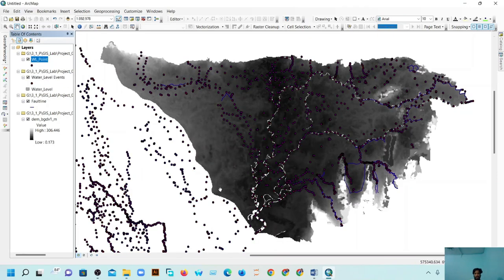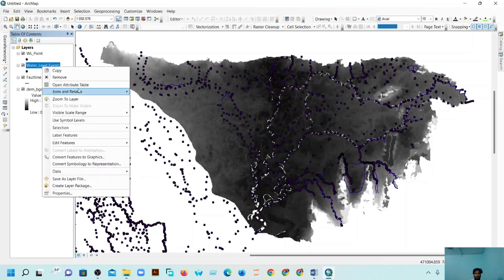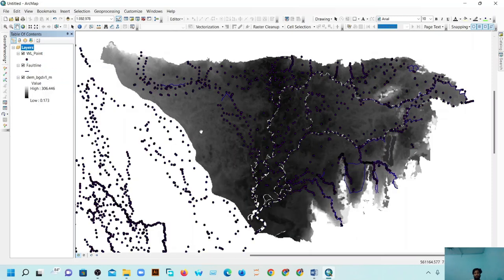Now we can remove the other layers of coordinate. As we know only the water level of some certain points, but not the whole area, we have to interpolate it to predict or assume a surface where flood occurs or not.